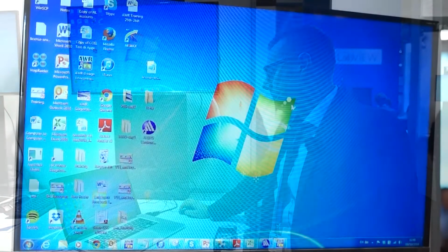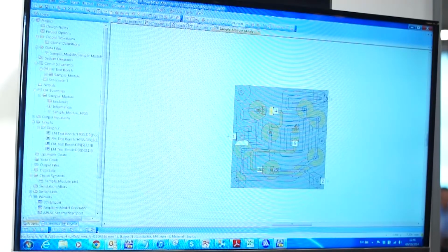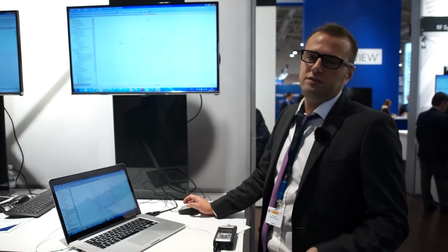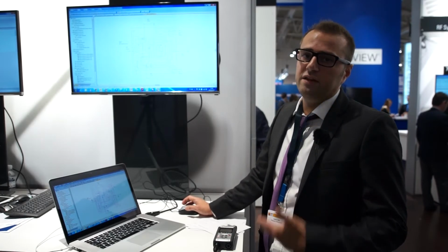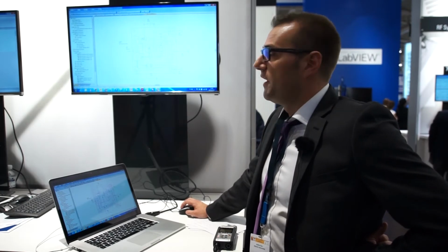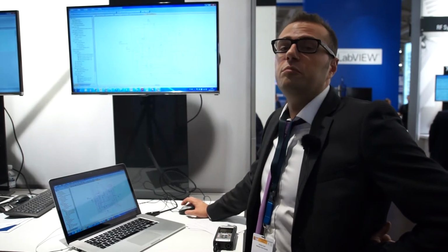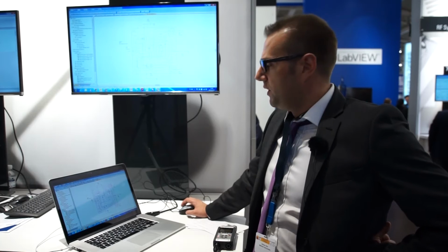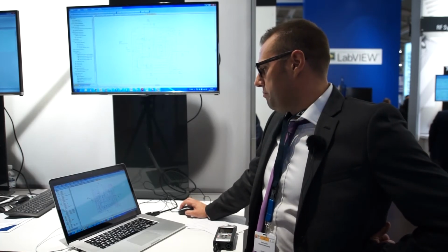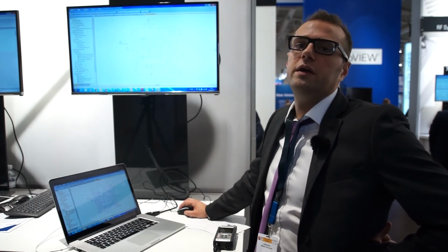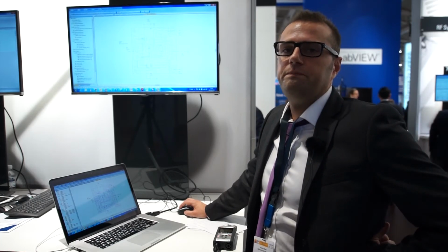So what I can do, now they are here in the data tree, is create a new sub-circuit and assign to this sub-circuit the S parameters data file generated by the Ansys HFSS simulation. And in this case, what I've done is I've used the symbol wizard provided by AWR to create a symbol that resembles the layout of my module. And as you see, there are some ports. I can reattach my circuit level model of the capacitor of my SMD components.